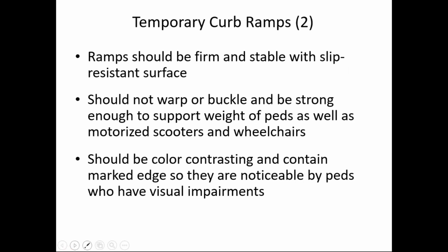Of course, the ramps need to be firm, stable, and slip resistant. They shouldn't warp or buckle. And remember, it's not just pedestrians or people in manual wheelchairs. Some people have what they call power chairs, the motorized chairs, which can weigh considerably more. They should be color contrasting and have a marked edge on both sides, so they're noticeable by pedestrians who have vision impairments, low vision pedestrians.